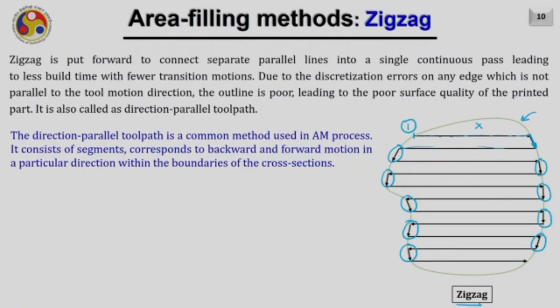It is also possible that we scan the layer differently. For example, this is the first layer and we are scanning it in the x direction. So the long passes are, you can see, in the x direction. Now if I want to scan the next slice, which looks something like this, it is possible that we scan the inside area at an angle from the x-axis.